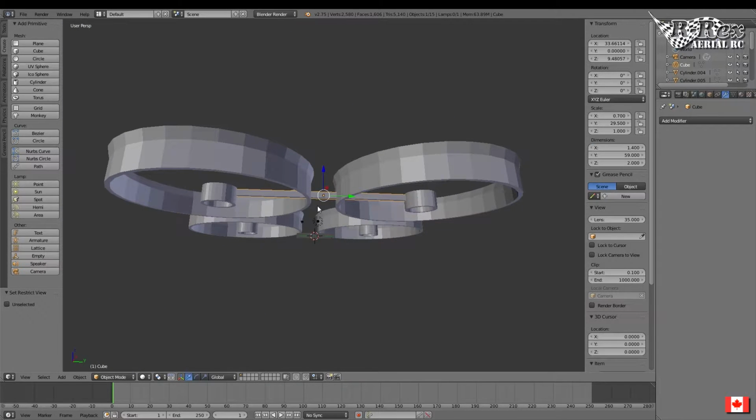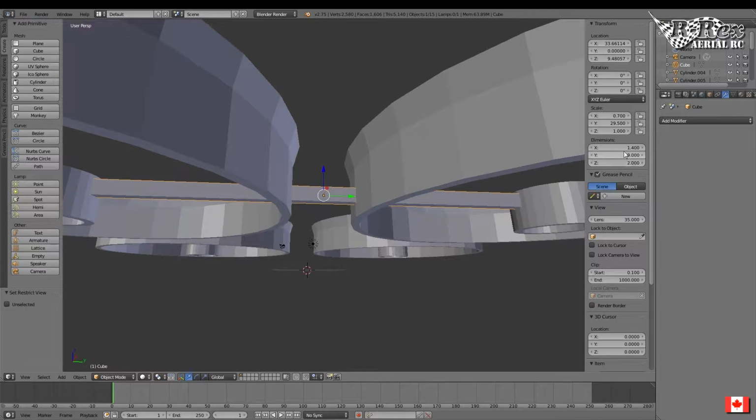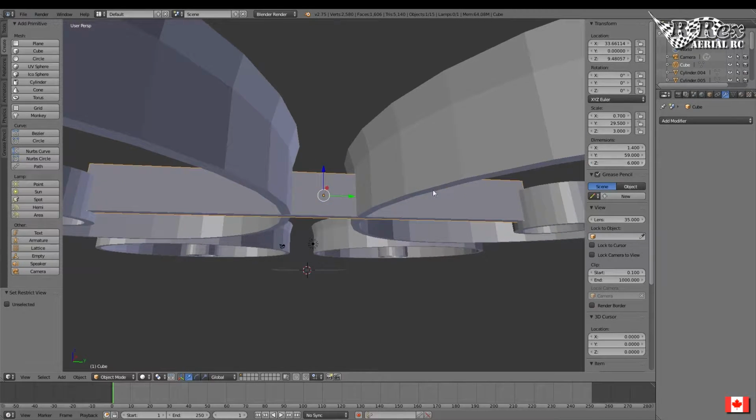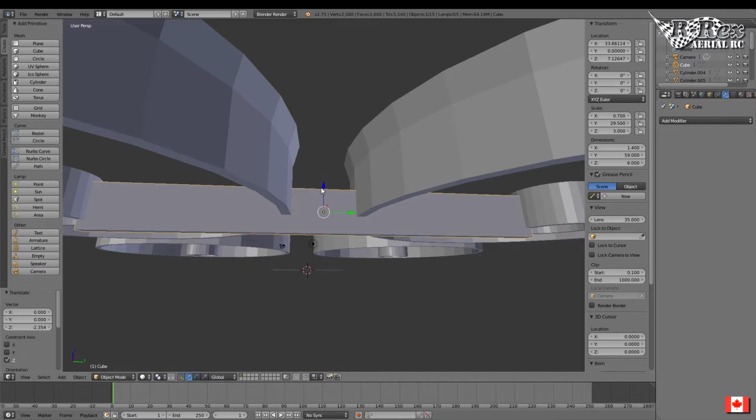Now I'm actually going to cheat and show you how to kind of clean all this up, because you're going to be printing from a 3D bed. So that bed is going to need, you're going to need to make sure the object is absolutely flat on the bottom. And instead of doing the math, I'm going to show you how to kind of overshoot everything and then just do a quick cut to line everything up onto a single surface. So let's go 6 tall, and I'm going to drop that down to, I say that's probably a good height right there.